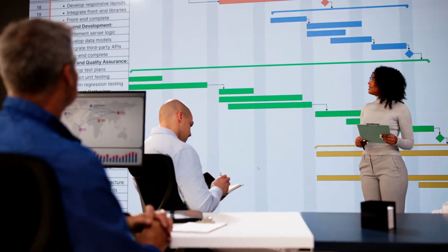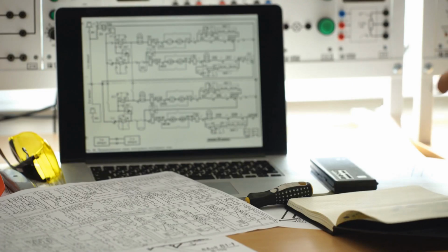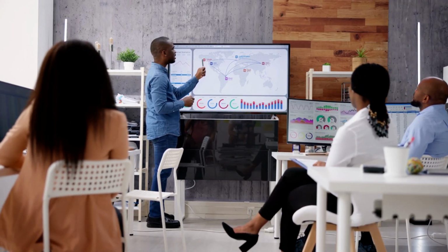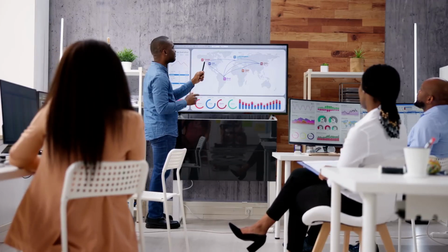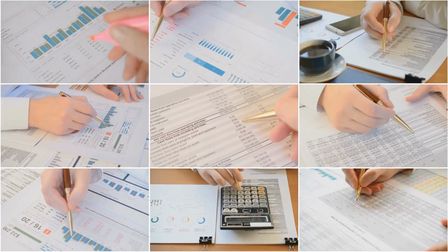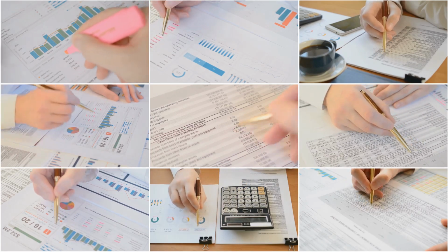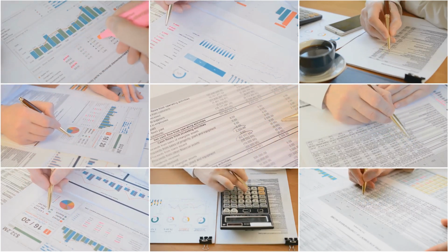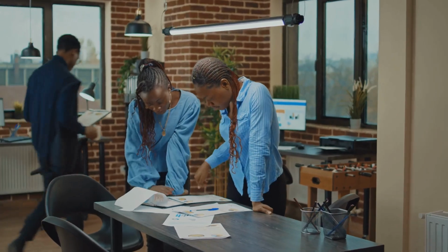Now it's time to institutionalize the fix. Update work instructions and SOPs, quality control plans, training materials, and certifications. Ensure all affected personnel are retrained. Monitor performance metrics to confirm improvement. If the problem involves suppliers, ensure they implement matching corrective actions and verify through audits or incoming inspection. The fix must become standard practice, not just a project.